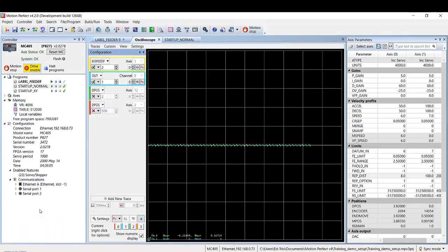Okay, so now we've made a modification to the program to trigger the move, instead of a position on the conveyor, on a registration event on the conveyor axis. So on a physical input. So when the input goes true, that triggers a registration and it triggers the move link, which has now a new trigger option. So let's take a look at that.